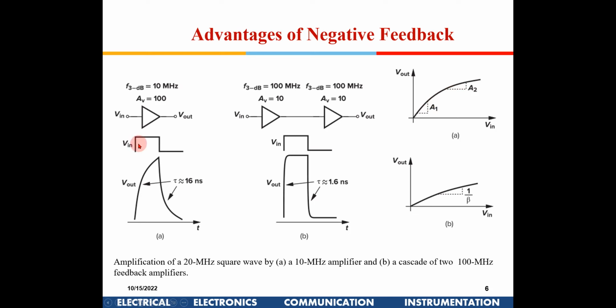So when you try to make one amplifier cater for the entire range, obviously it will come out of the saturation region. So you can't. When you split it into small operating regions, then accordingly you can do the sizing of the transistors and make it linear. Is it okay with all of you?